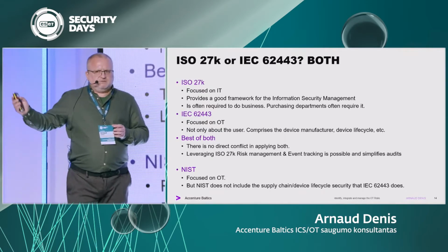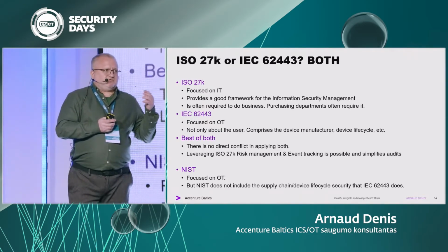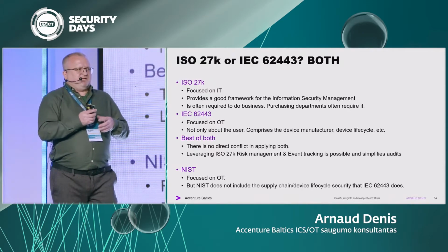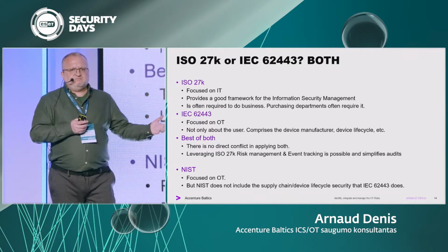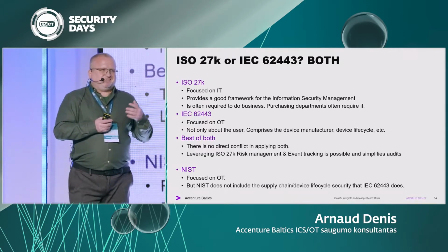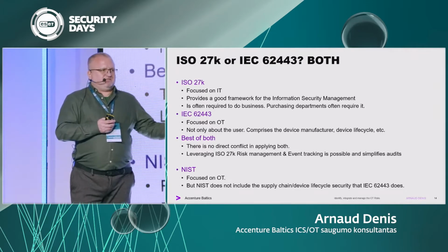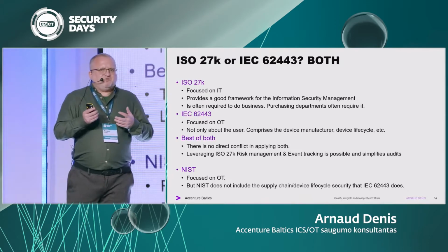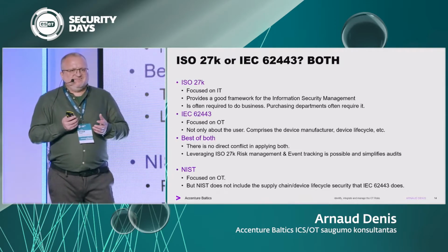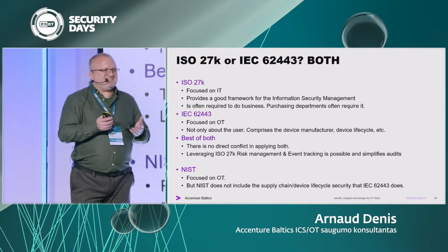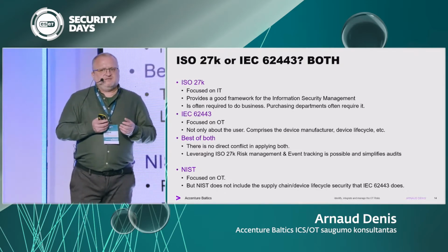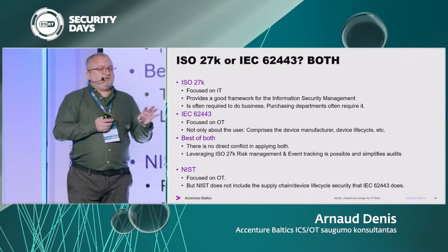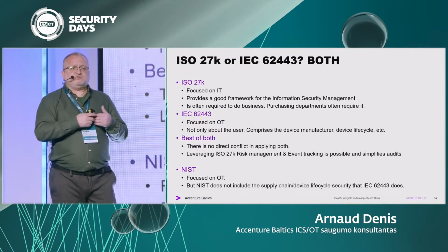Secure development lifecycle, okay? That means that contrary to before where they would produce some equipment and then disband the development team and move on, what they are now saying is, well, actually you need to keep it running for all the time it's going to be alive. Now OT systems tend to be 10 to 20 years, even sometimes more. So if you think of all the IT systems you have that have lasted that long, you really have to concentrate on that. And that's why IEC 62443 is good for stuff you buy and also to deploy.